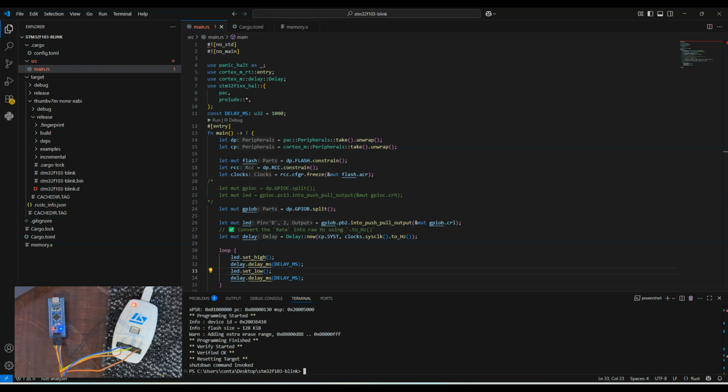That is the question: why couldn't we use the ELF format? There are some tools like probe-rs that can flash ELF files, but OpenOCD or st-flash expect raw binaries.